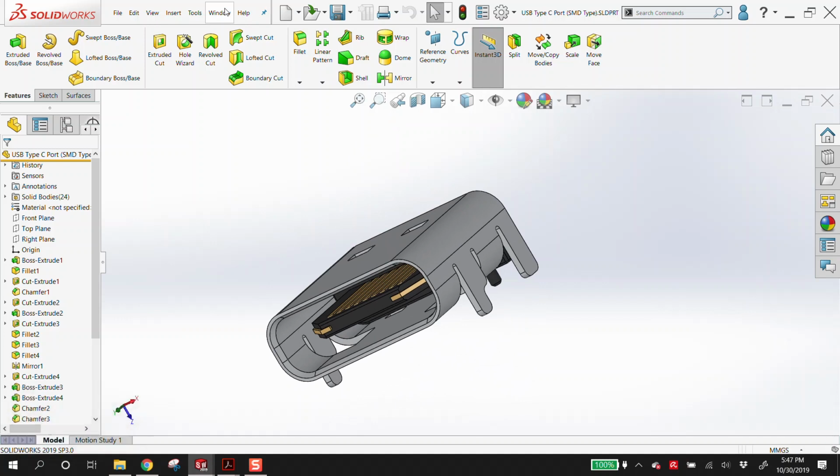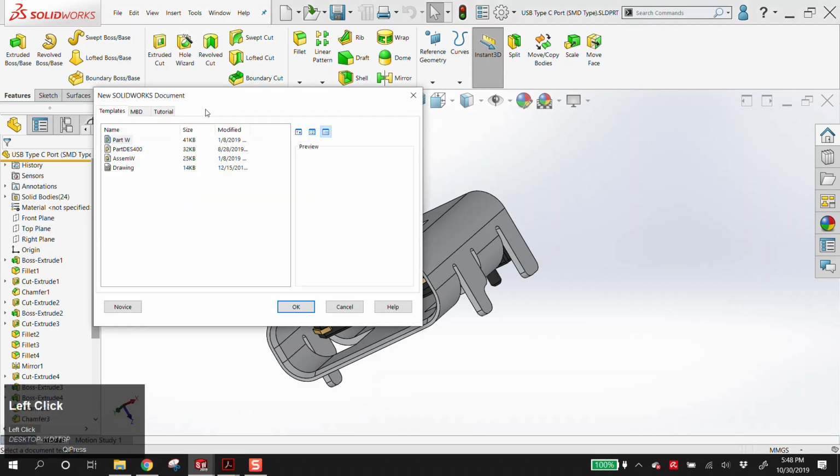So okay, step one, gather your components. Step two, open them, check them out, save them out as SolidWorks parts, okay? And that's kind of what this says here on the sheet. That gets us, again, through step two. Step three is how to create the underlay which you're gonna work within. So what that asks you to do is to create a new assembly. So file, new assembly.